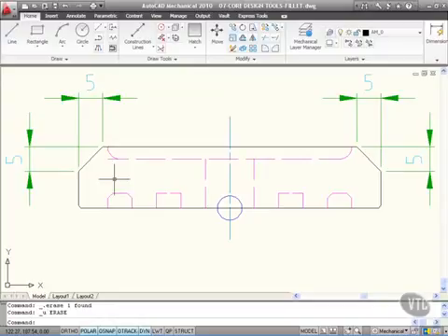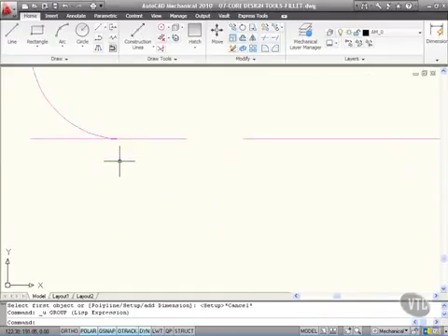So what happened there? Let's just check that one again. You can see there that there was obviously an extra line somewhere, because when I did that fillet, it didn't fillet to that line there. So all I need to do this time is just click on that line there and take it to the end of that arc there. It's easy, but zoom in so you're nice and tight. Roll up on the wheel there on the mouse.